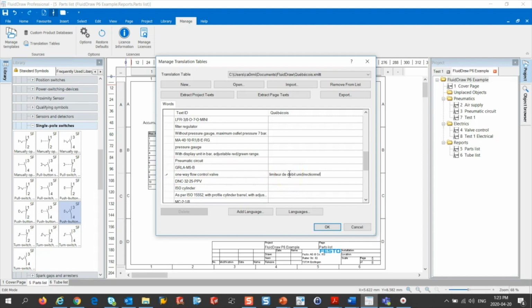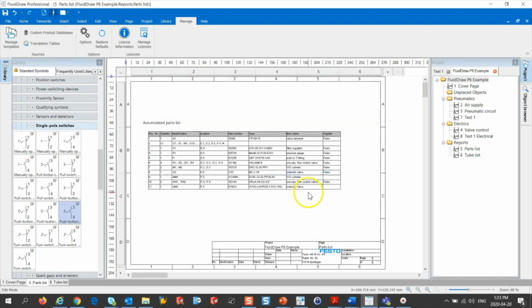This can take into account local variants for components. If there is something in a specific industry that is jargon-based, that is not in the translation table, instead of modifying each component, you can select a translation table and give yourself that jargon term so it's clear and concise in the industry you're looking for. Once we click OK, nothing happens. Why? Because we have to actually set the language that we're using.